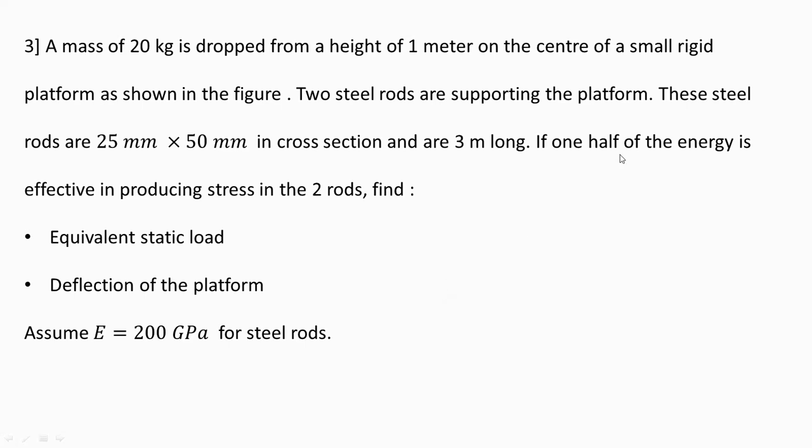So half of the energy is effective in producing the stress. This is the important part. We have to first find out the energy and then take half of that to find out the value of stresses or value of static load and deflection of the platform. Now as the weight is falling from a certain height, it is the case of impact loading.